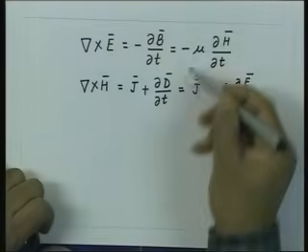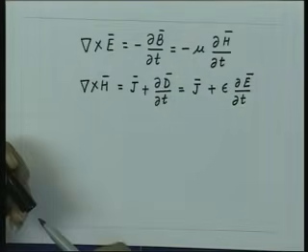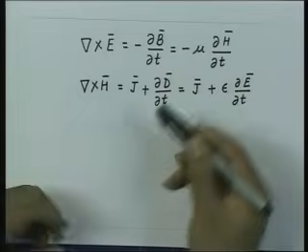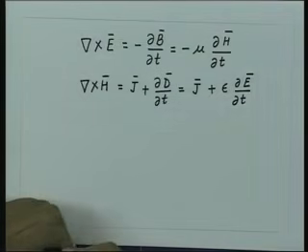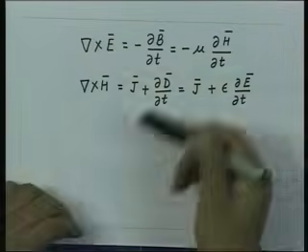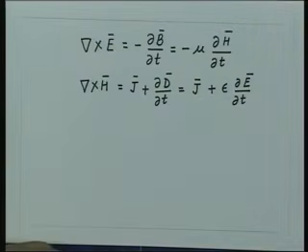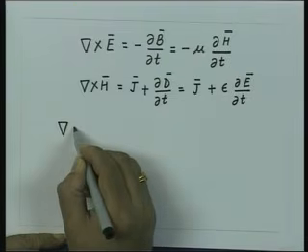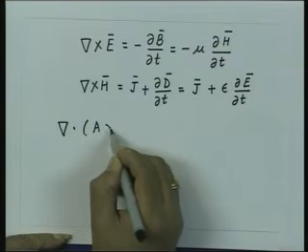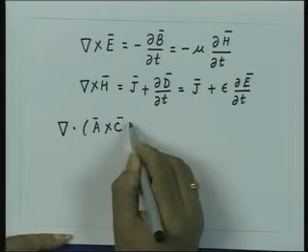So, again we start with these two basic equations and then try to investigate the power flow associated with the electric and magnetic fields. Here essentially we make use of vector identities and then try to give meaning to some of the terms which we get in the expansion of the vector identity. Let me take the vector identity del dot A cross C, where A and C are two arbitrary vectors.